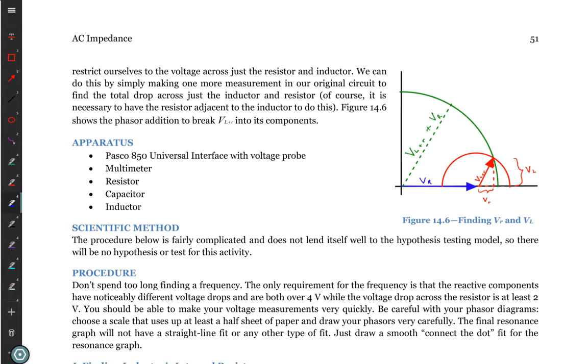So you're going to use your compass, which I had to pull out to make it go long enough, and set it. Notice you can loosen it here, adjust it, and then tighten it so it holds its length. Set it so your distance is that 12 volts, and then draw a semicircle that starts at the end of V capital R and has that radius of 12 volts.